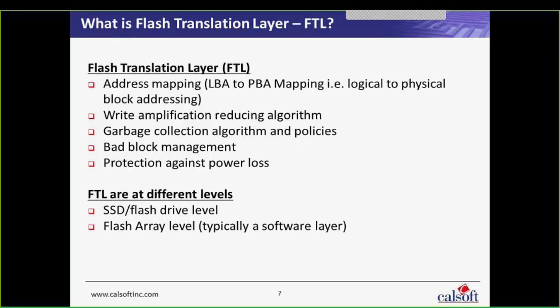And then we have a bad block management engine written inside the FTL to manage all the bad blocks which are coming through the cycles of write on your Flash-based storage. And then protection against power loss is again a case-to-case kind of feature that all Flash arrays implement.